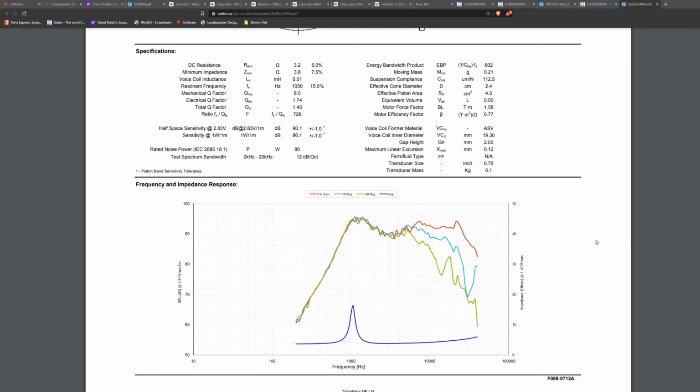Other tweeter types have better or worse beaming tendencies, and compression drivers in horn-loaded systems can have different dispersions as well, and it's just a matter of tailoring it. But with the way this rolls off here, mainly focusing on our 30-degree curve, it's still better than AM radio.